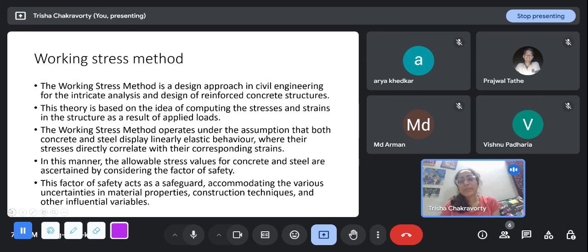So that is why we apply these factors of safety, so that even if there are certain factors going against us, that is the material that we are using is weaker than what we assumed, or the load somehow comes more, our structure will still be able to withstand it. Of course, again, reliability is how safe a structure is. We cannot take the reliability up to infinity, we have to draw the line somewhere. But these factors of safety actually account for the uncertainties.